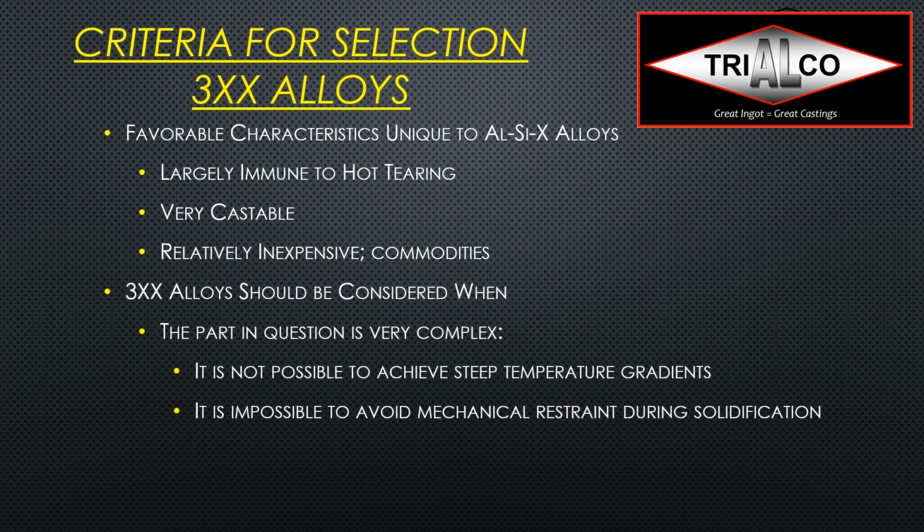They should be considered then if the part in question is very complex, if it's not possible to achieve steep temperature gradients and very directional solidification, and it's impossible to avoid mechanical restraint during the solidification.